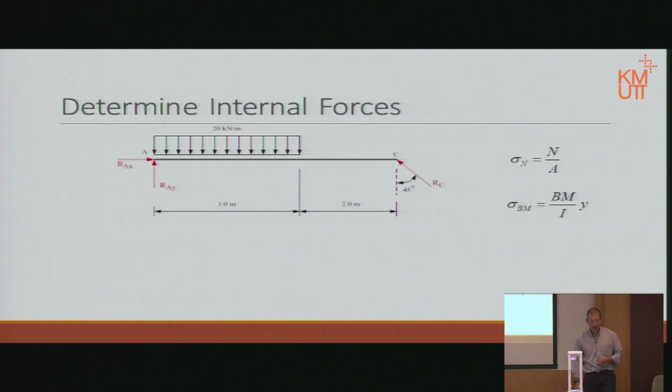Now to find axial force, to find internal forces in this picture, we need to find out the reactions first through the total free body diagram. The three equations, three unknowns, the same step we have done all the time: sigma Fx equal to 0, sigma Fy equal to 0, sigma moment equal to 0. Not necessarily in that order. After we apply all three equations, we should get all three reactions.